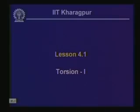Welcome to the first lesson of module 4, which is on torsion part 1. If you remember, we had discussed in the last 3 modules aspects of stress, strain and application of stress and strain on thin walled pressure vessels. Now, if a bar is subjected to an axial pull, it is subjected to a normal stress which we have seen as load divided by the cross sectional area. Consequently, we have seen that if the bar is subjected to axial pull, it undergoes deformation, which we have defined in terms of strain, the deformation relative to its original length.